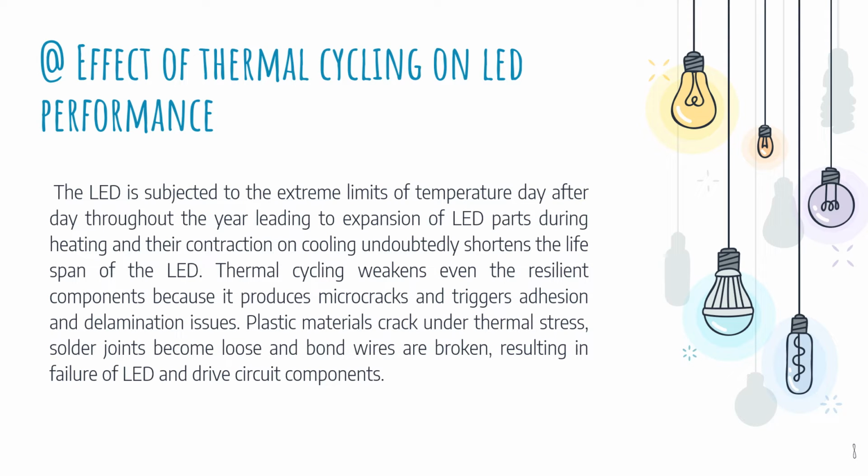As an effect of thermocycling, the LED is subjected to the extreme limits of temperature day after day throughout the year, leading to expansion of LED parts during heating and their contraction on cooling, undoubtedly shortening the lifespan of the LED. Thermocycling weakens even resistant components because it produces micro cracks and triggers adhesion and delamination issues. Plastic materials crack under thermal stress, solder joints become loose, and bond wires are broken, resulting in failure of the LED and drive circuit components.